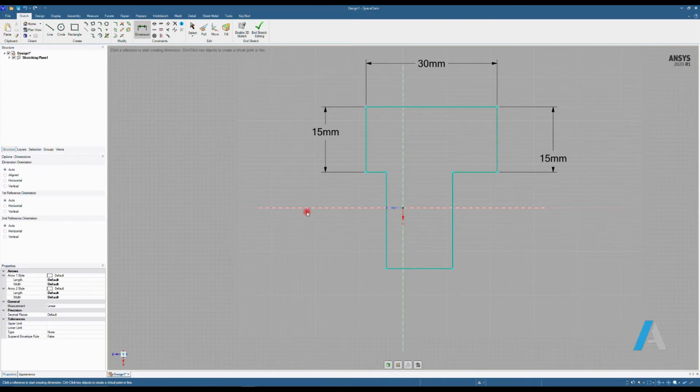There are many ways that you can fully define your sketch. You can define all of them dimensions, you can define different constraints to fully define your sketch. But you have to make sure if you are a professional CAD user, you don't have the same dimension defined multiple times in your CAD model.